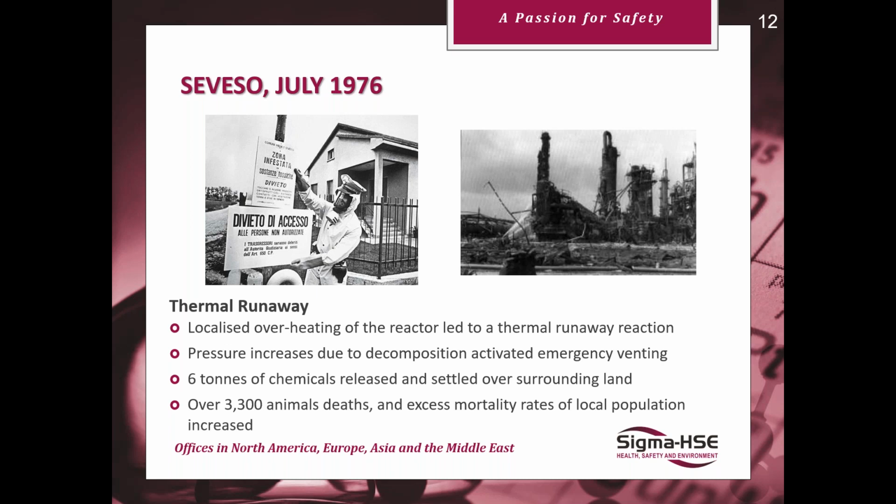As pressure was generated, the emergency venting system did activate, but just due to the thermal runaway reaction, it couldn't vent enough, and as there was no stirring, the thermal runaway reaction just continued. And 6 tons of these chemicals were released from the vent and settled in the surrounding area. There were no directly linked human deaths, a lot of animal deaths, and a huge cleanup operation following. They were manufacturing disinfectants and cleaning agents in this place.